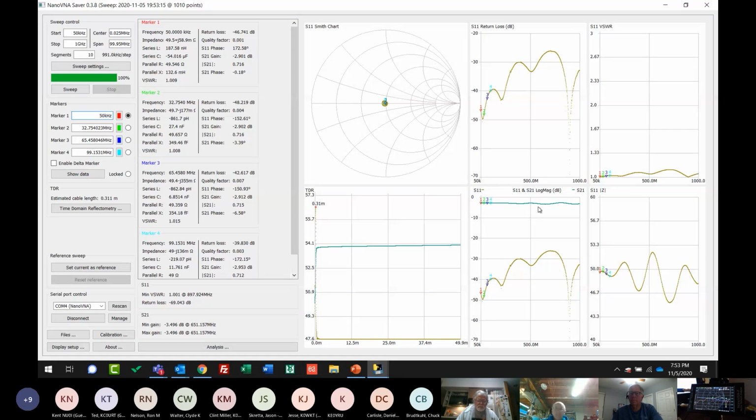We can also see up right here, if we change the data axis here, and it's currently doing an automatic span. We could adjust this so that we can see, but this is our 3 dB, 0 to 10 to 20, and this is our S21 parameter, or our through parameter, and we're seeing that that's acting exactly as we would expect it to there. Let's jump to a couple of other things.